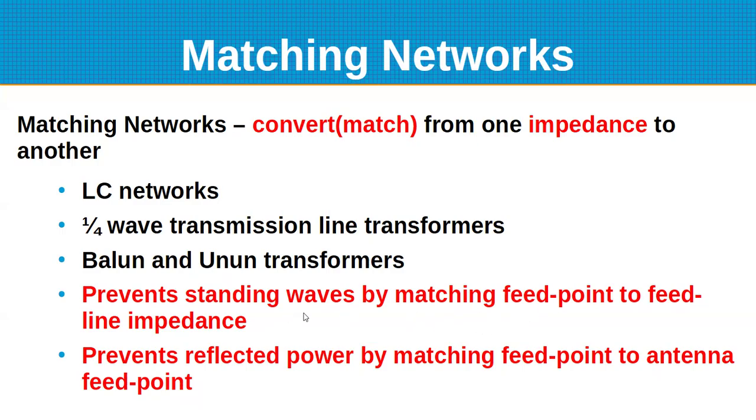It says it prevents standing waves by matching the feed point impedance to the feed line impedance. That's really only true if it's at the antenna. If it's down at the receiver end, it's not affecting the standing wave ratio that's on the feed line.